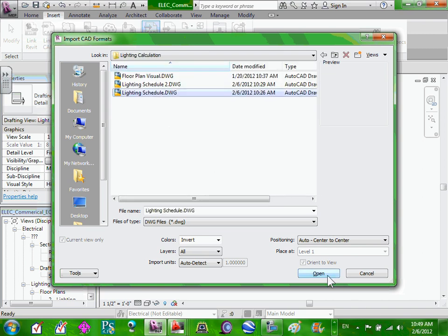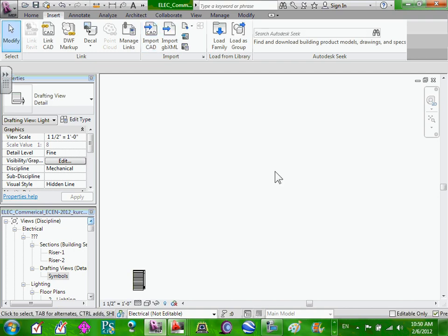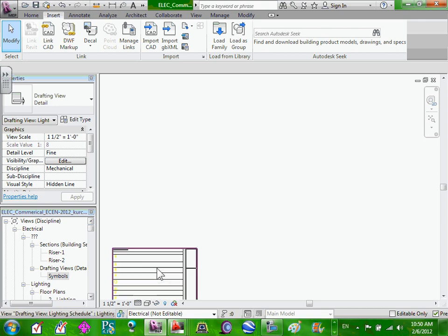Here's the lighting schedule. Open it. So grab the lighting schedule, you open it, you brought it into Revit. You can explode it in Revit and work on it too. And this is how you bring anything from CAD. And then you drop it. You have a view of it. Now you can drop it into the right sheet. Let's stay linked. No, the minute that you bring it, you are doomed.